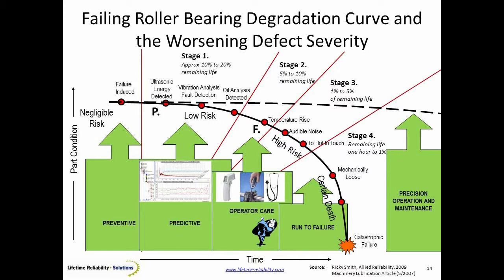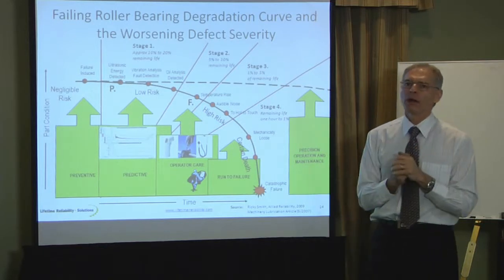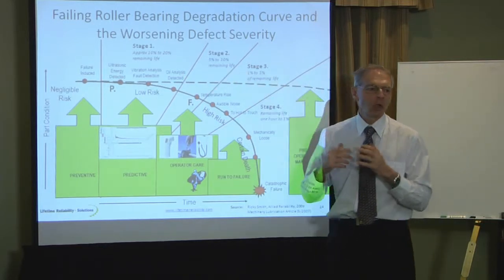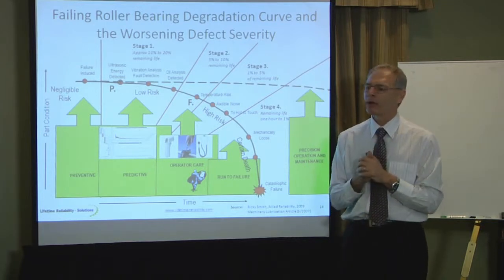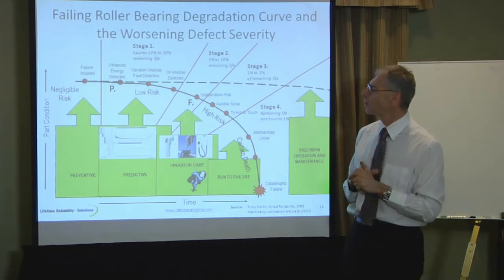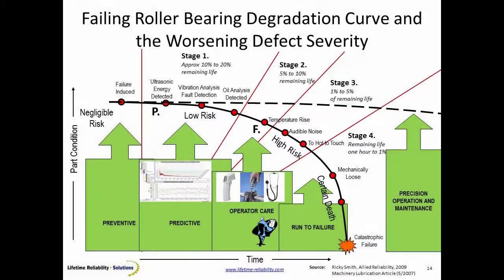Condition monitoring, the methodology of that is to find this P point as early as possible, to find where the trouble is becoming evident, and then before this bearing actually causes a problem, to replace the bearing. The problem starts at the F point, the functional failure point. By the time it's here, that bearing is unsuitable to remain in service. That machine is in serious trouble.